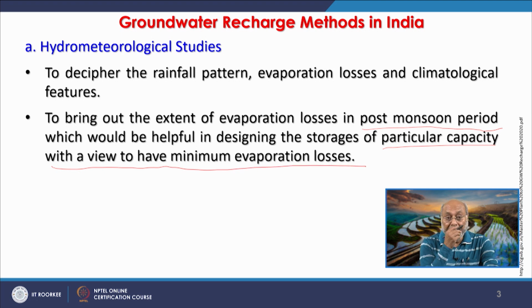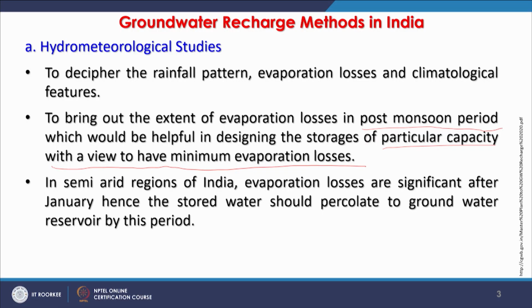While designing these groundwater recharge structures, we will be creating a large surface of water, and if there are water losses through evaporation, that may be a concern. For example, in semi-arid regions of India, evaporation losses are quite significant, especially after January when temperatures start rising.